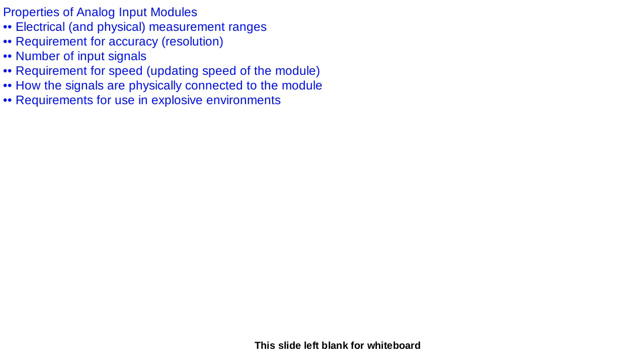Also, the calibration and adjustment. When we talk of calibration, we mean: can you add a bias to the measurement to compensate, for example, for a poorly installed sensor or transmitter, so as to compensate for the voltage drop over long cabling. And the last criterion that you can consider is the filtering possibilities.